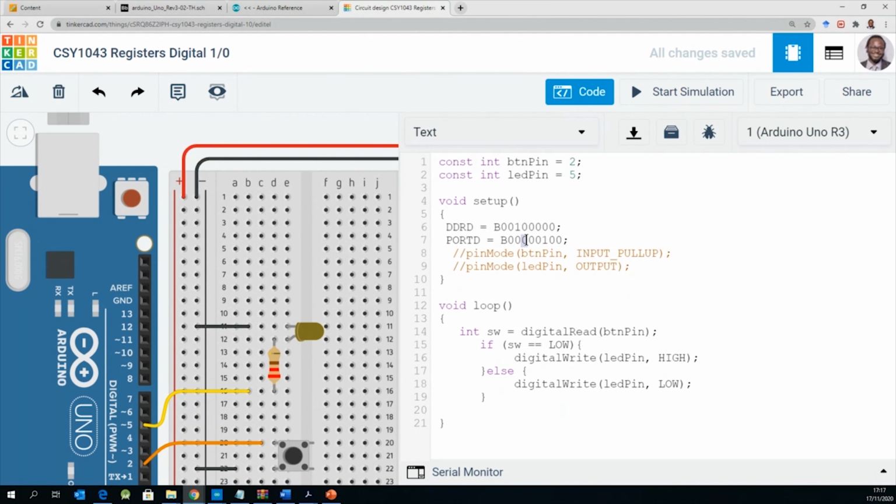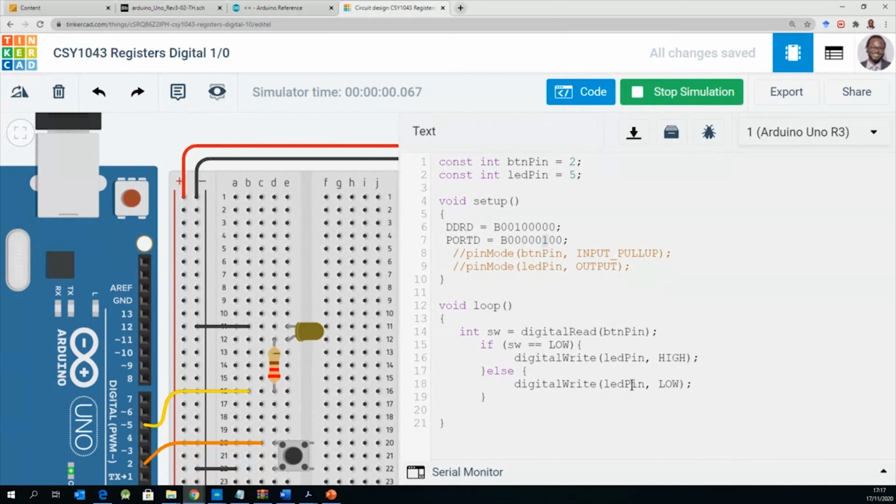So far we put the switch off, we put the LED off. We had it being put back on at this point and nothing else happening. And then we've set the switch to input pull up, because when we run it, at the moment, the LED is off. And if I press, the LED comes on, which is the behavior we expected before.